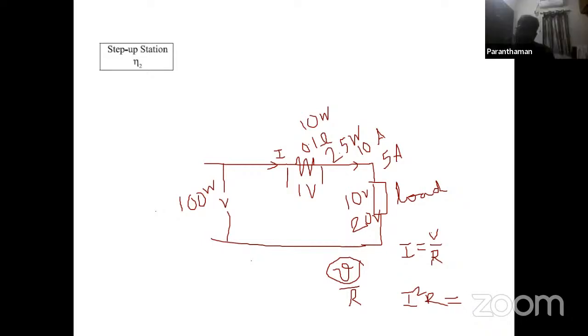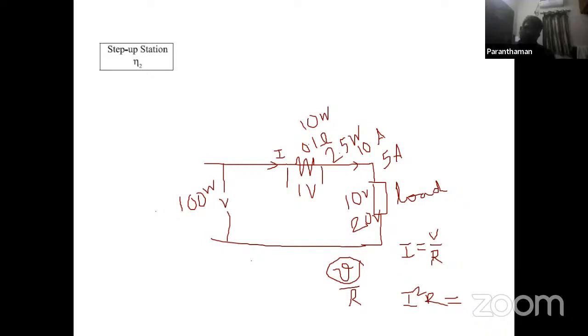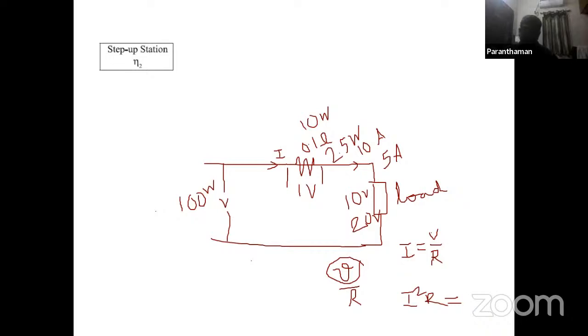And comes the motor. The motor efficiency is 0.9. Into 0.9. Lastly comes the mechanical power, the mechanical coupling and everything. The mechanical power has the lowest efficiency. It will be losing much energy in the mechanical coupling. It is 70% only, so we have to multiply it with 0.7.